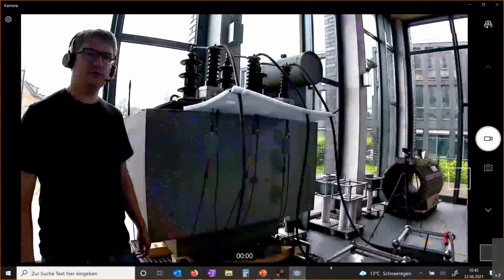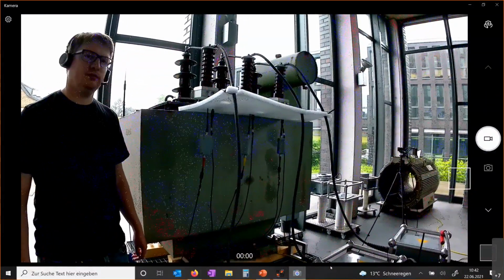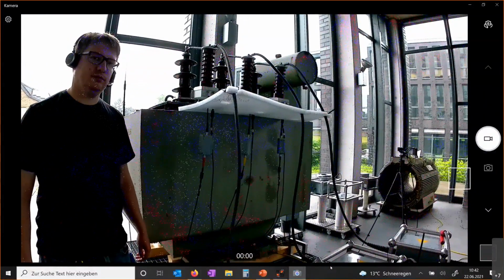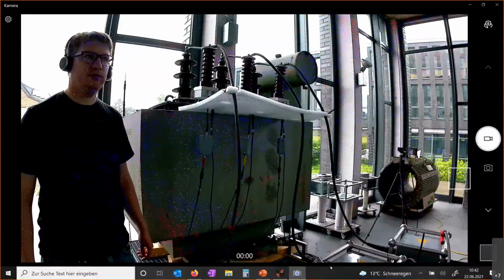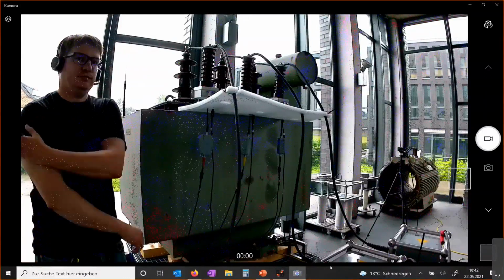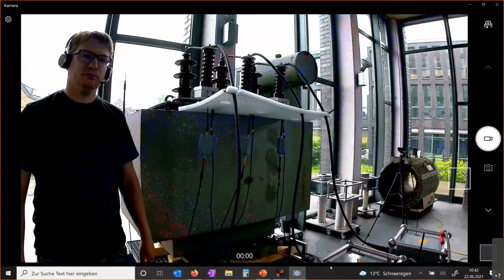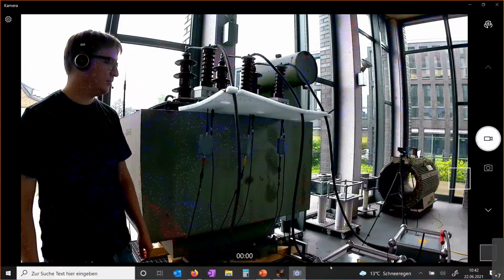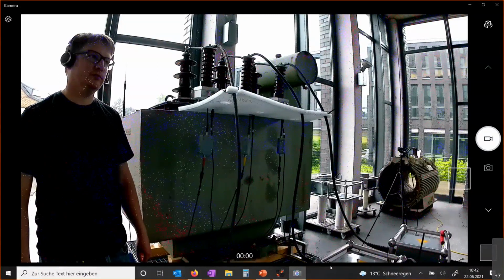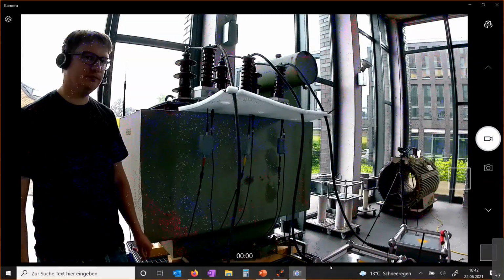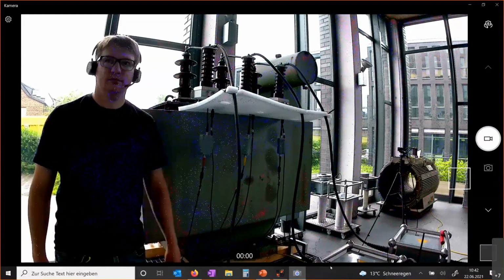PD is like a specific pain location in your body. If you have knee pain, it's different. You can have a knee pain, for example, or a specific location pain issue. That's PD. So PD locates a problem in specific areas like floating particles, sharp points, fiber bridges in the oil, tracking discharge, voids, delamination. Localized issues in a specific location, that is PD. However, the overall condition, the aging of the insulation, that's the tan delta.